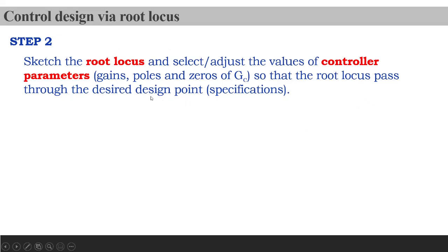That's really interesting. So now design point would be visible on your S-plane, and you want to customize your root locus to pass through that particular design point, and that's the point. So how could we do that?